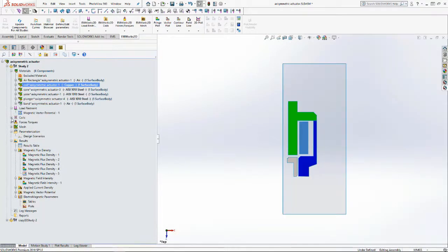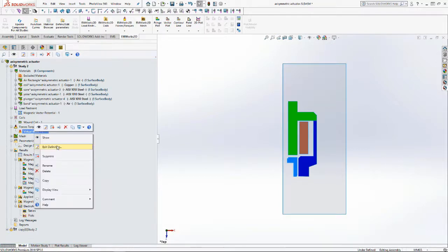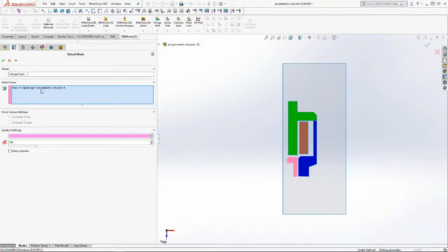After that, you define the boundary conditions, starting with this condition: magnetic vector potential set to 0 on the outer edges of your problem. Then create your coil if you have a coil, or a magnet. The minimum required excitation is a coil or a magnet. You can also define where you want to compute the force, whether a force or a torque. In this example, for axisymmetric, we only support force calculation. When we have a planar problem, we can compute both force and torque results.